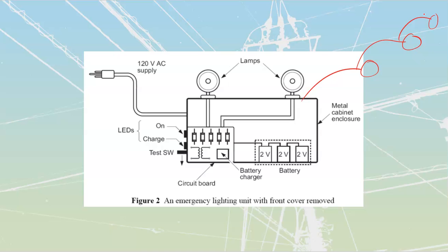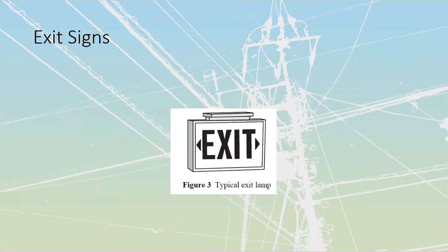Exit signs, a little bit different. These ones over here. Exit signs themselves are going to be mounted either on the ceiling or on the wall. They are going to be red or green. They sometimes have knockouts towards either end that are these arrows so that you can use them to direct people towards the exits. So in some cases, we'll have these things blanked over. If I can blank that one. Yeah, I can blank that one. And then if this thing was pointing down a hall, you would have to remove that knockout so that it directs people towards where that exit actually has to be. If you do not need the arrows on there, don't take them out. Leave them inside. It does not actually meet code if you remove them, because you're directing people away from the exit at that point.